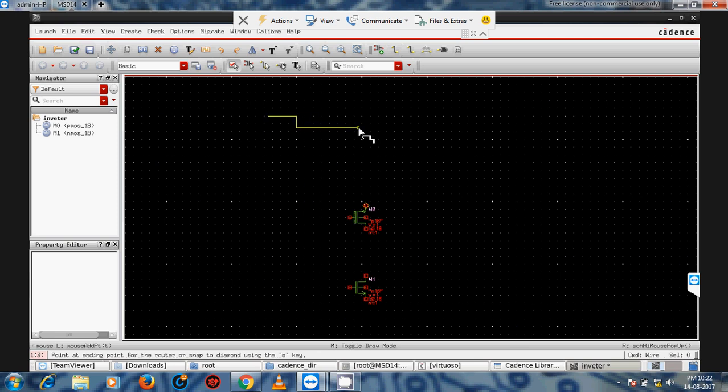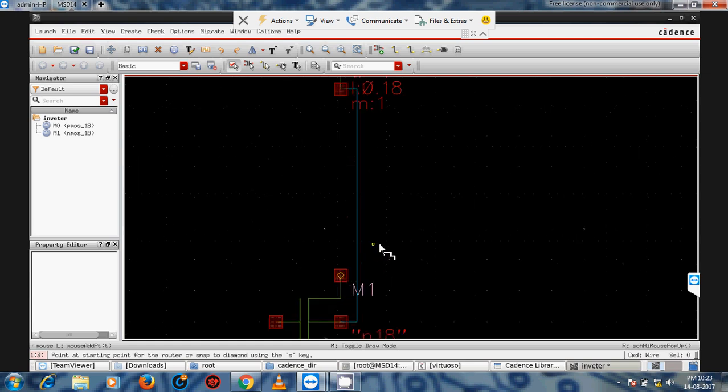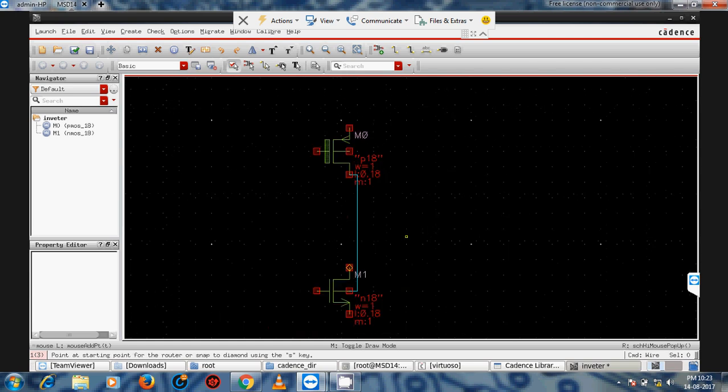So now go to wiring. Here a wrong wire was created, so if you want to delete, firstly press escape, so this will free from wiring. Now click the wire and press delete, so automatically it deletes, or otherwise firstly click delete, a mouse cross will appear, and click which component you want to delete.